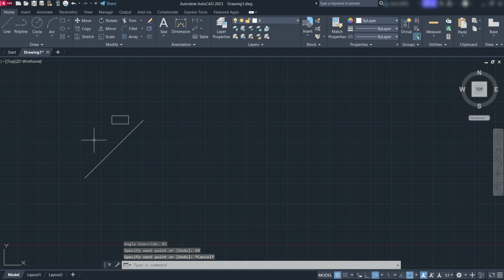There are many other ways of making a line. If you want to make a line using a single command, type at. It is related to the relative coordinate system. Then enter the length. Let's make 30 and then press the angle sign, which I have already told you, right beside M while holding the shift key, and press the angle in which you have to restrict that line.